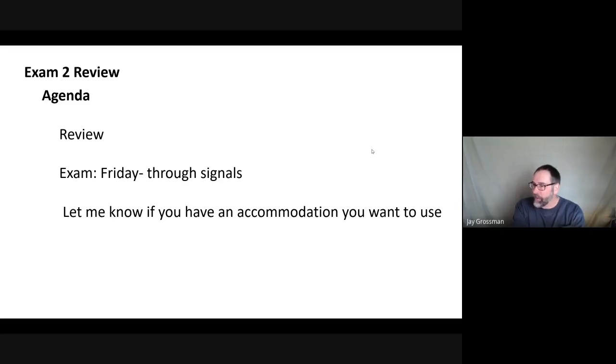Yes, you can ask questions about the project at the end. Optimal green time. The book says round up to 5 seconds, correct? I don't agree. I say round to the nearest 1 second. I'm going to write another note for that, and that was for cycle lengths. The book says around 5 seconds, but I've never done that in practice. We always use the nearest second, and so I would recommend that for cycle lengths. I'll try to make that specifically say in the question: round to nearest second. How's that?